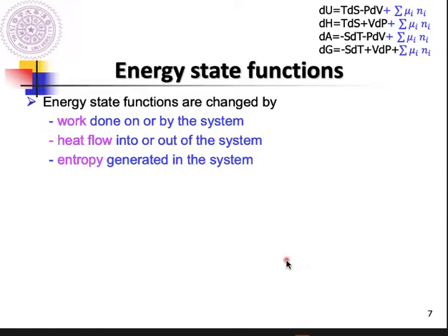Okay, let me give you a brief summary of the energy state functions we just introduced, including the internal energy, enthalpy, Helmholtz free energy and Gibbs free energy. The energy state functions are changed by what? By the total work, including the mechanical work and non-mechanical work done on or by the system, and also by the heat flow in and out of the system.